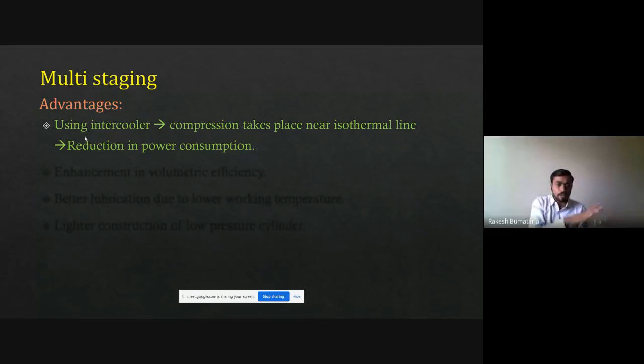But when the compressor in the first cylinder compresses from 1 to 8 bar and delivers at 8 bar pressure, there is definitely a rise in the temperature of the air also. So there is always a higher temperature than atmosphere. And due to the rising temperature, the volume of air gets increased, and it is not advisable to operate with a large volume of air. So there is a heat exchanger known as an intercooler between the lower and higher pressure cylinders.